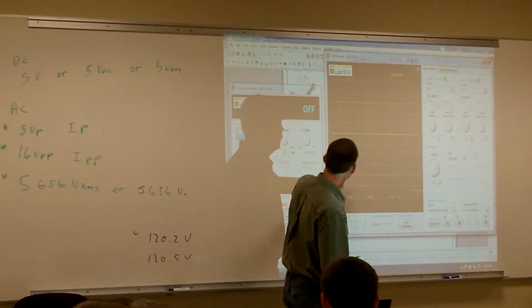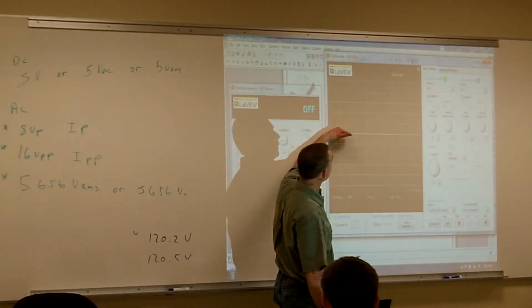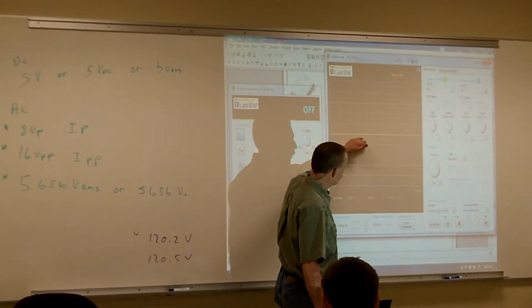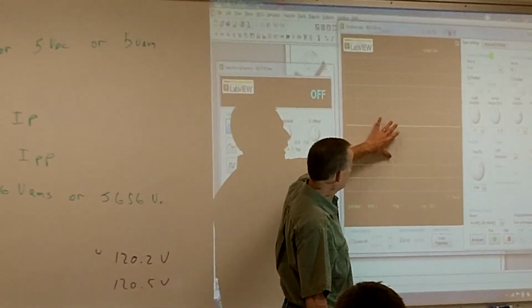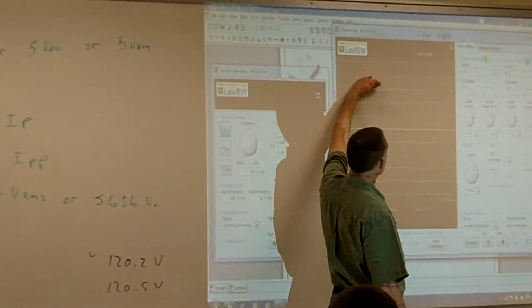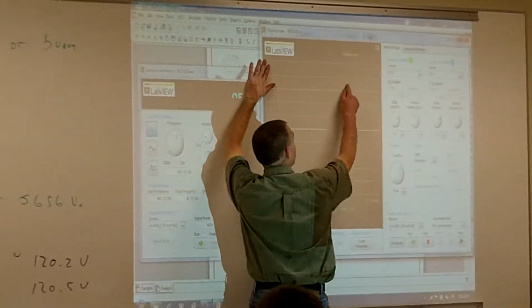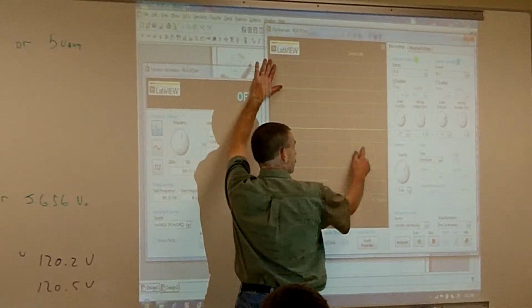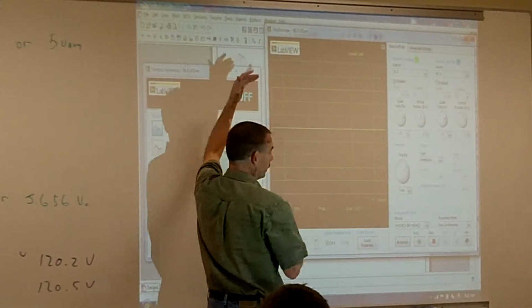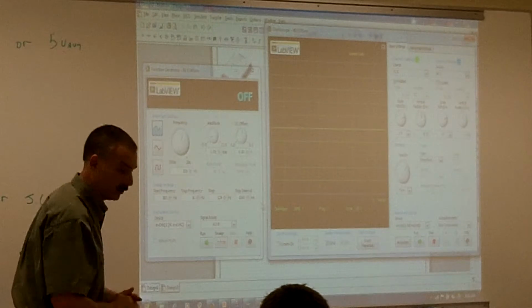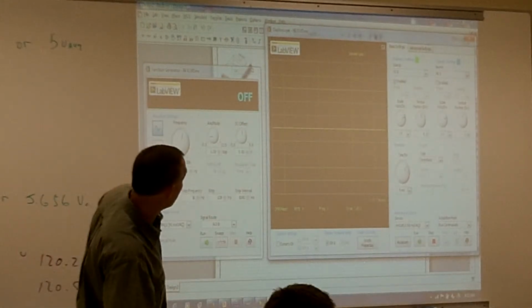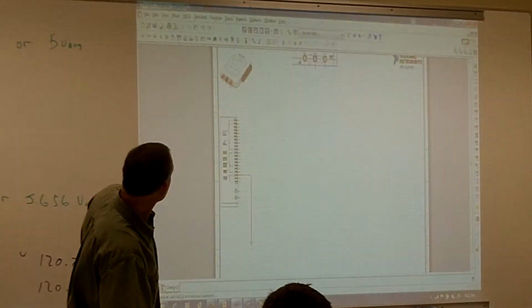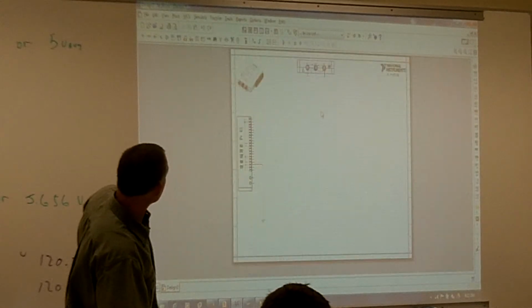But anyways, what you can do is that if I have it hooked up going through the Multisim and have it going through my function generator, I can actually display what my waveform looks like in my simulation, and then below it I can measure my actual circuit. So you can compare the two signals and stuff like that. So there's some cool stuff that you can do with it if you want to take it that far.